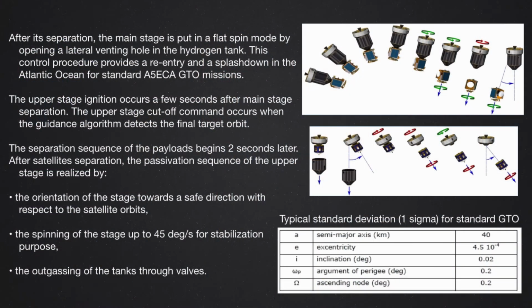orbit. At that point, the upper stage of the launcher with the satellite performs a three-axis maneuver around the three axes, which are roll, yaw, and pitch, in order to separate the satellite in the appropriate separation direction, because all the satellites are different. All the satellites have specific thermal and sun constraints, so they have separation directions which are very, very specific.